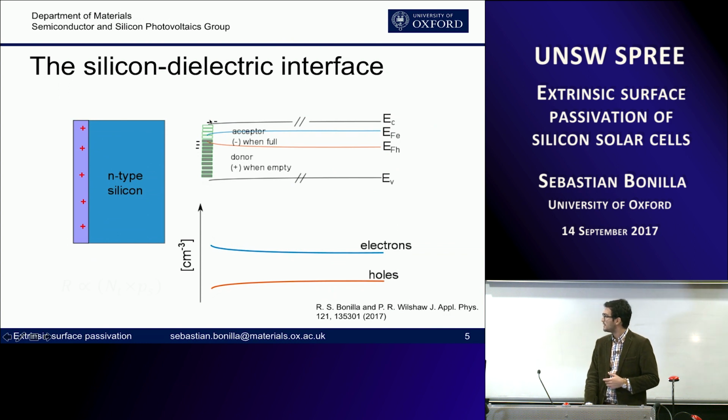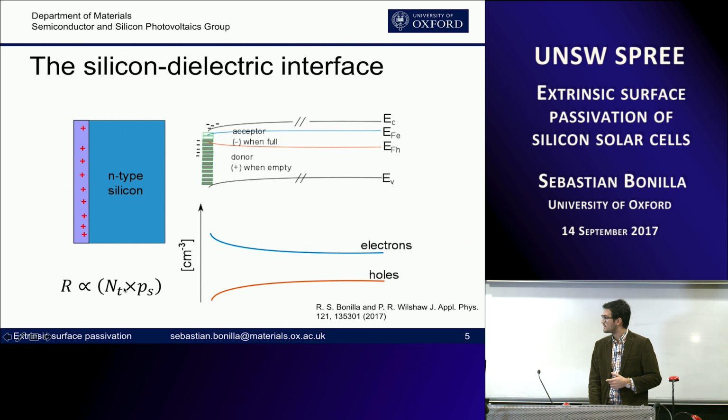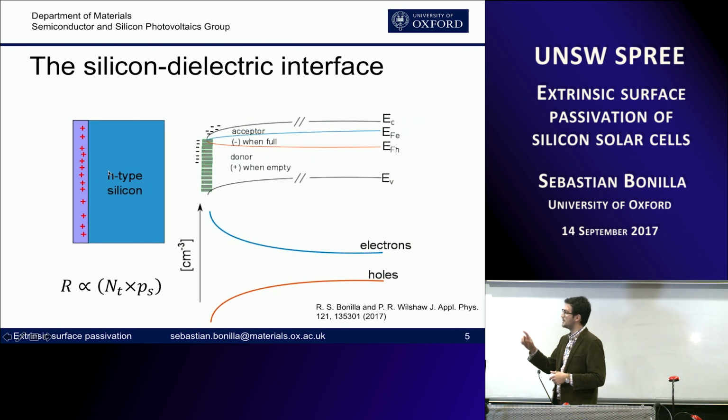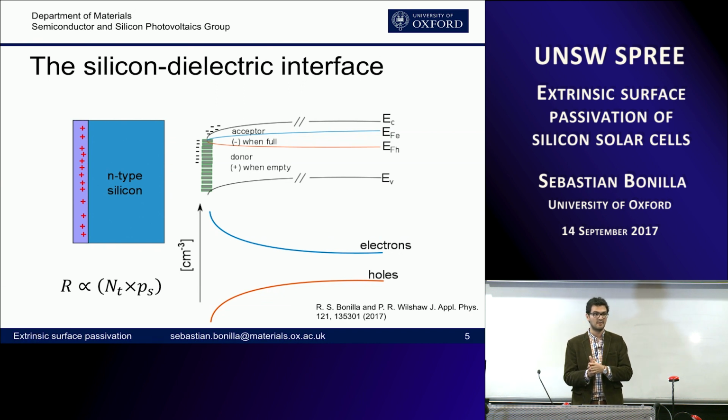And it's important to remember that when we are reducing the recombination rate, we want to reduce the number of carriers at the surface. In this case, we want to reduce holes at the surface, and these holes are the concentration there and there. So what actually happens is that when we have a concentration of the charge of the dielectric being mirrored as charge in the interface states, that makes field effect passivation less effective, right?